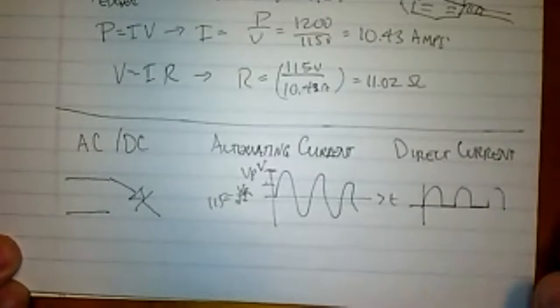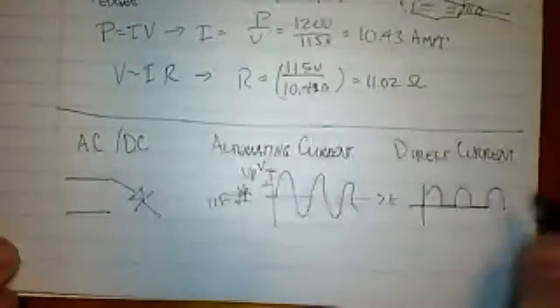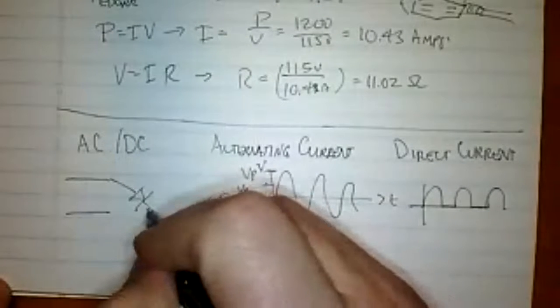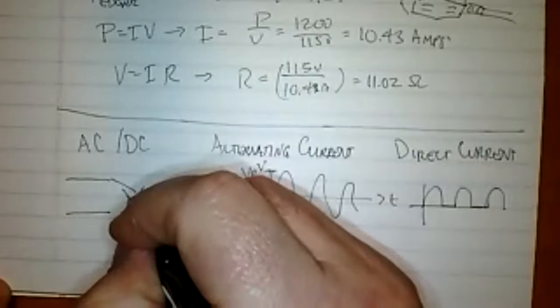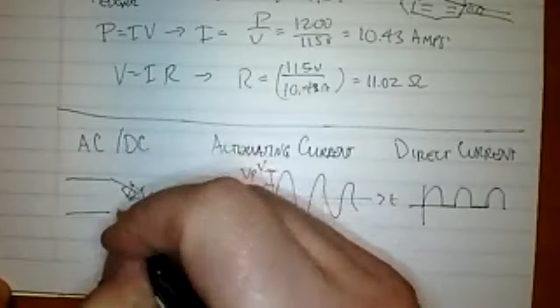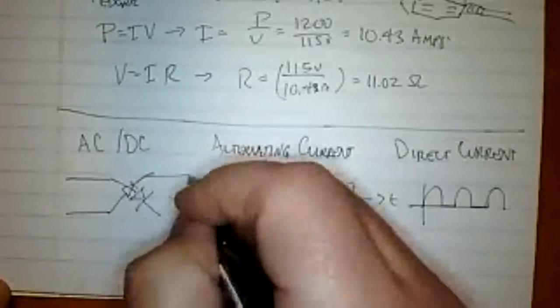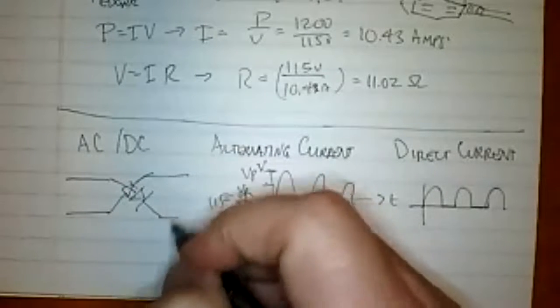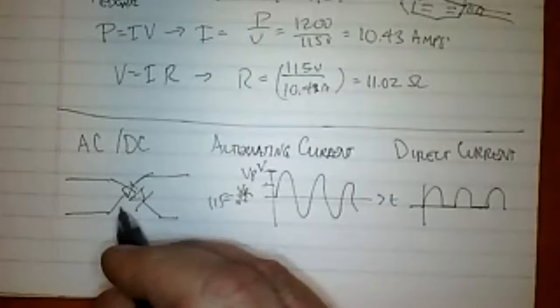So you'll get a series of humps like that. That's a half wave rectifier. There's a way where you can actually connect it to a full wave rectifier by putting another one this way. So when the current is going the opposite way, it actually allows it to come out as well. There's some other parts that have to be done with this, but you can sort of get the idea.